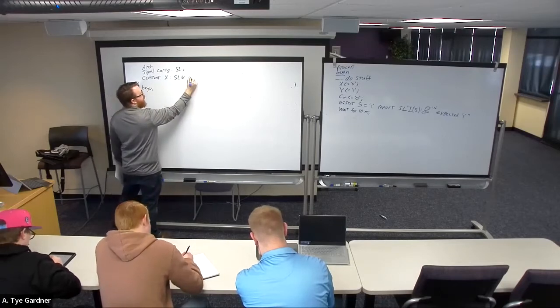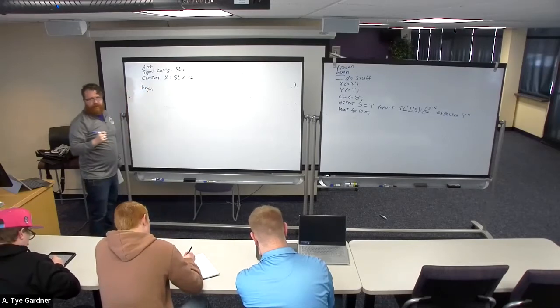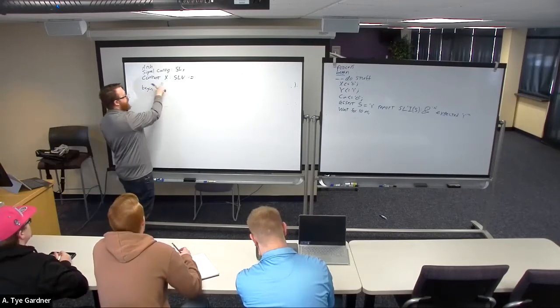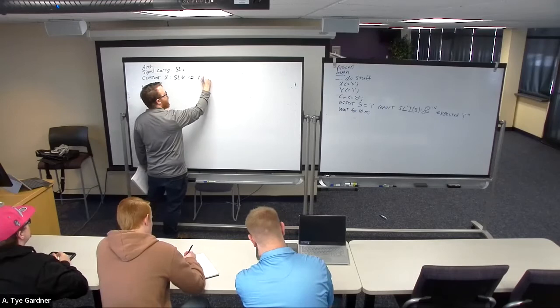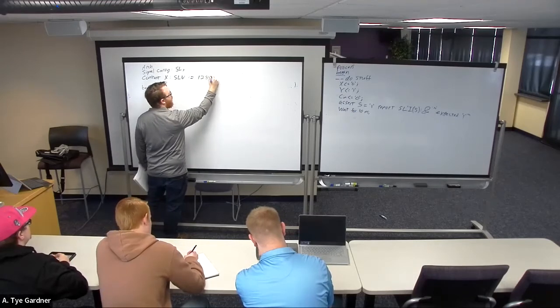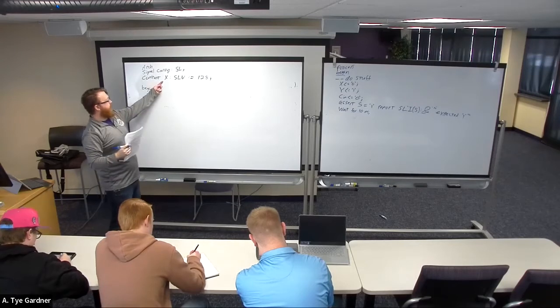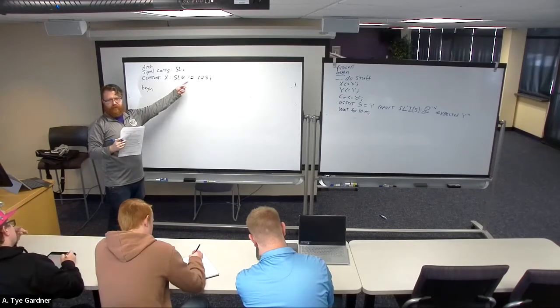The difference is that for a constant I have to give an initial value, which we do by putting colon equals. And if I want X to be 128, there we go. Now, anytime I write X, I'm getting a standard logic vector.